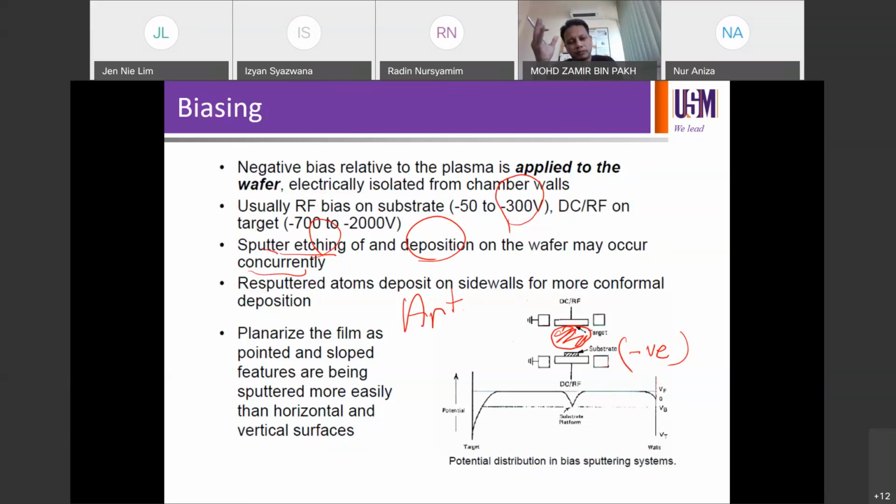So it's a bit counterintuitive because you are actually doing deposition. Sorry, that one is for the target. If you apply on the substrate side where you want to have the deposition, so while you have plasma colliding on the target to do the sputtering. So for example, you have plasma colliding on the target here on the top side to do the sputtering of ITO, for example. At the same time, you also enhance collision rate of argon plus on the silicon side.